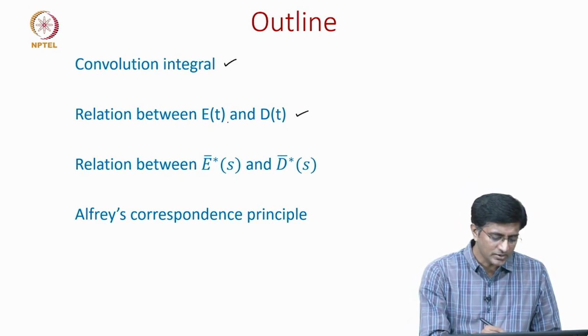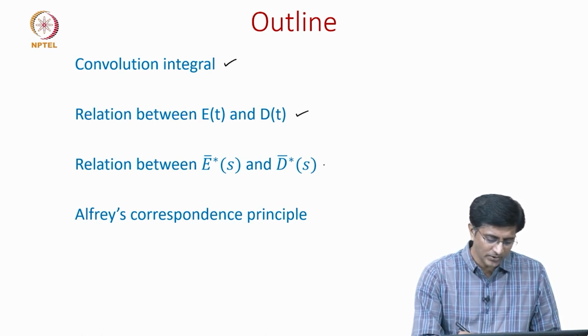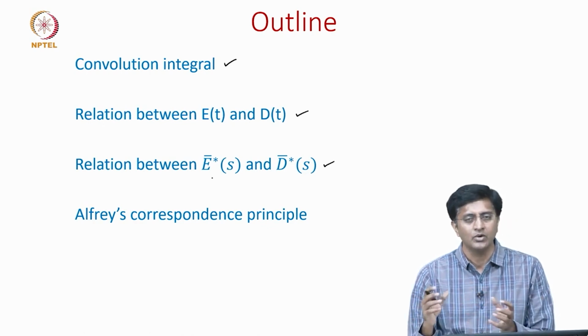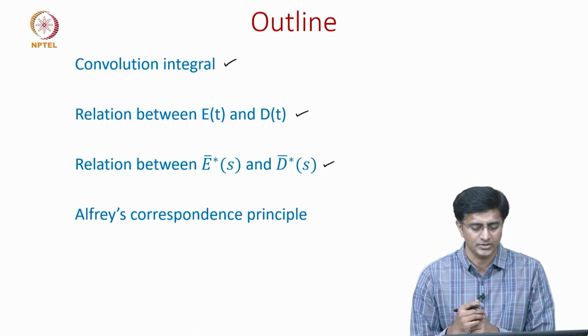So, we will see what the relation is in the time domain, E of t and D of t. We will also see what the relation between these two is in the transform domain, meaning we will take the Laplace transform and see in the Laplace domain what the relation is between the elastic modulus and the creep compliance.